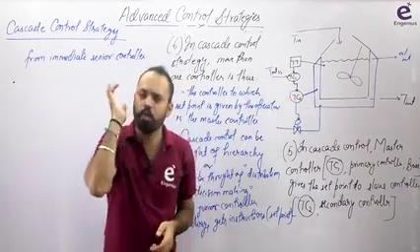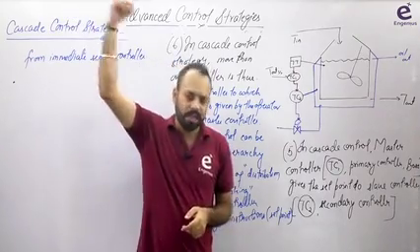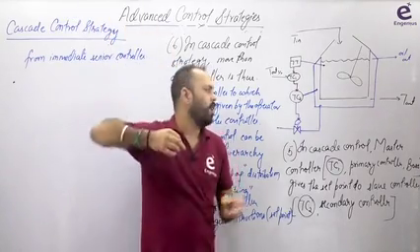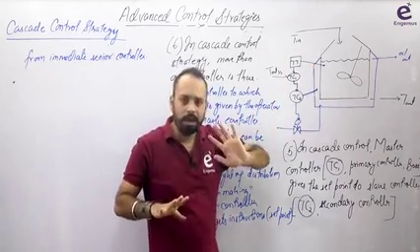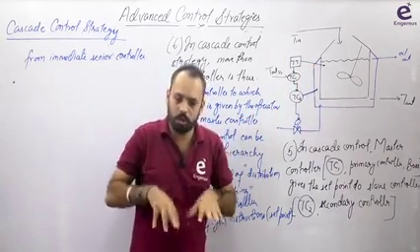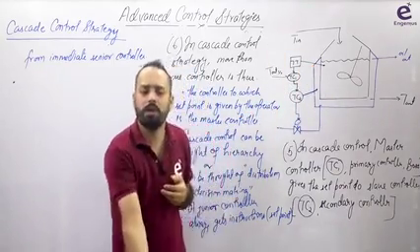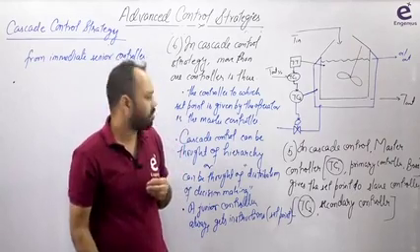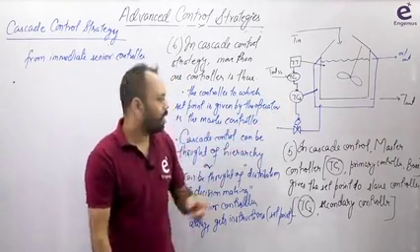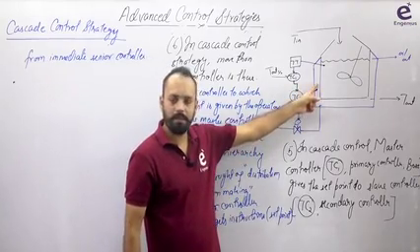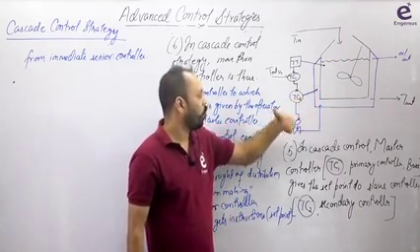TC2 को. नाउ TC2 नोज, TC2 इज रिसीविंग इंस्ट्रक्शंस फ्रॉम हिज सीनियर दैट आई हैव टू मेंटेन द जैकेट टेम्परेचर एट 75 डिग्री सेल्सियस. नाउ TC2 अगर उससे खुद हो रहा है तो कर देगा, नहीं तो वो अपने नीचे एक और कंट्रोलर को हायर कर लेगा. TC2 can say कि okay, I will give instruction to the junior controller that for maintaining this jacket temperature, what should be the flow rate.